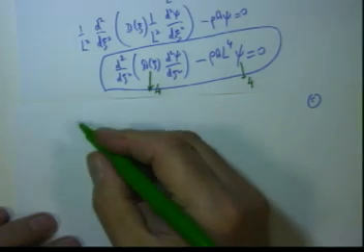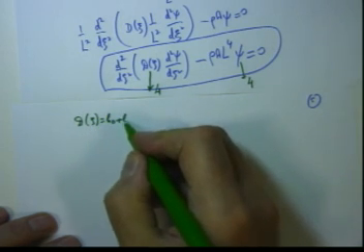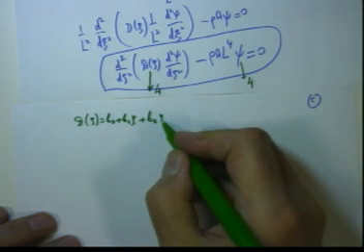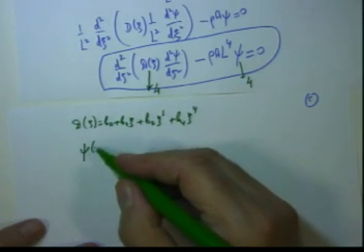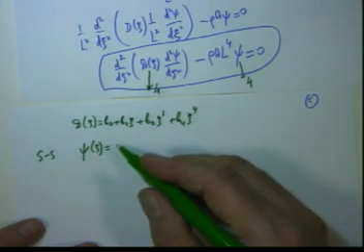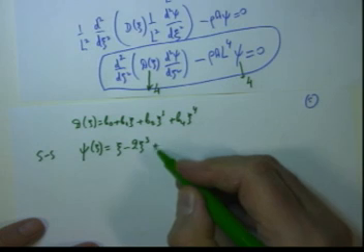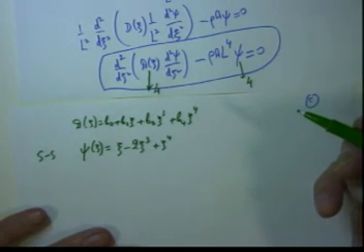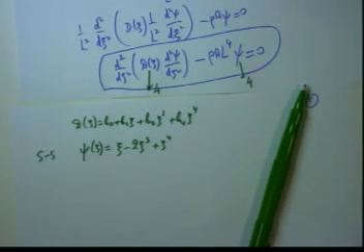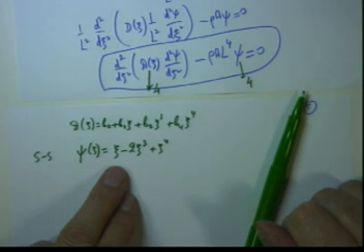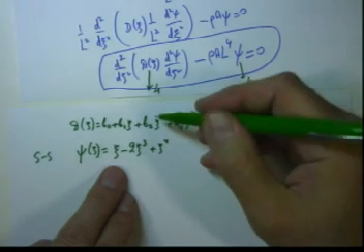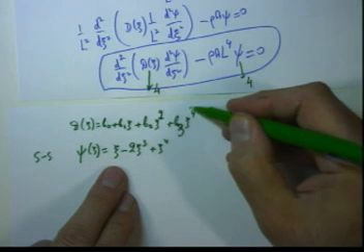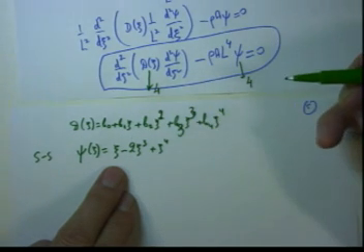So therefore d of psi equals b0 plus b1 psi plus b2 psi squared plus b3 psi cubed plus b4 psi in fourth power. Psi of psi, so it is simply supported, equals psi minus 2 psi cubed plus psi in fourth power. No, psi squared will be for clamped, and this is for simply supported, is just psi. Here: b2 psi squared plus b3 psi cubed plus b4 psi in fourth. Yes, thank you.